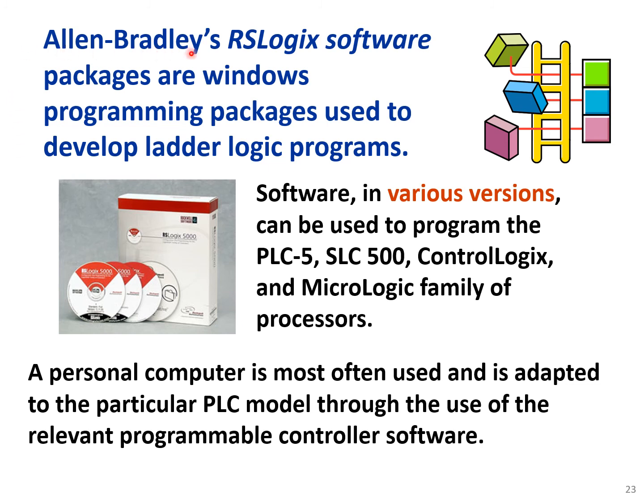Allen Bradley's RSLogix software packages are Windows programming packages used to develop ladder logic programs. Software in various versions can be used to program the PLC-5, SLC 500, ControlLogix, and MicroLogix families of processors. A personal computer is most often used and is adapted to the particular PLC model through the use of the relevant programmable controller software.